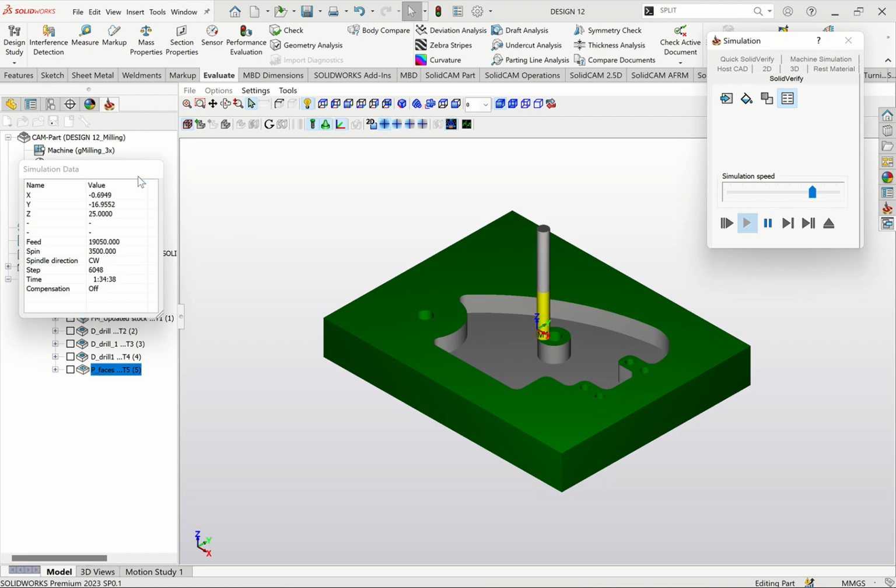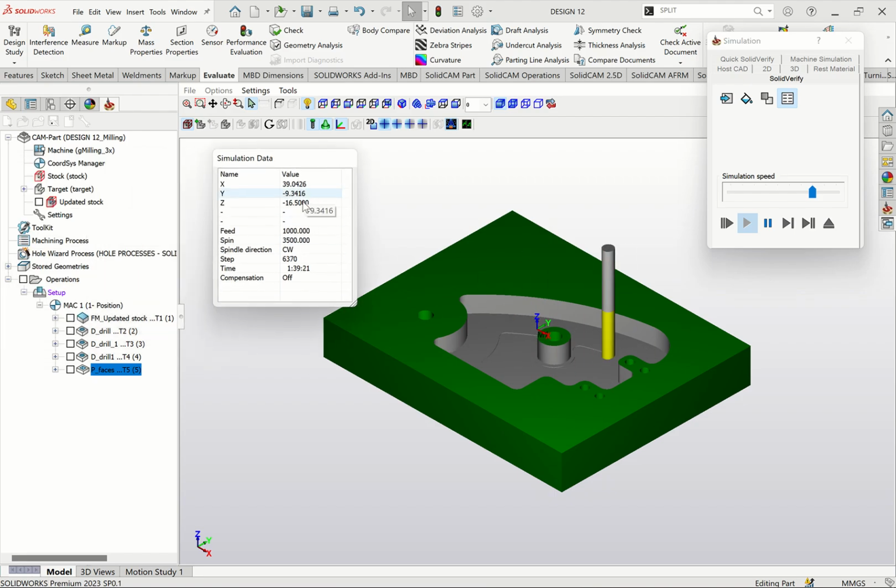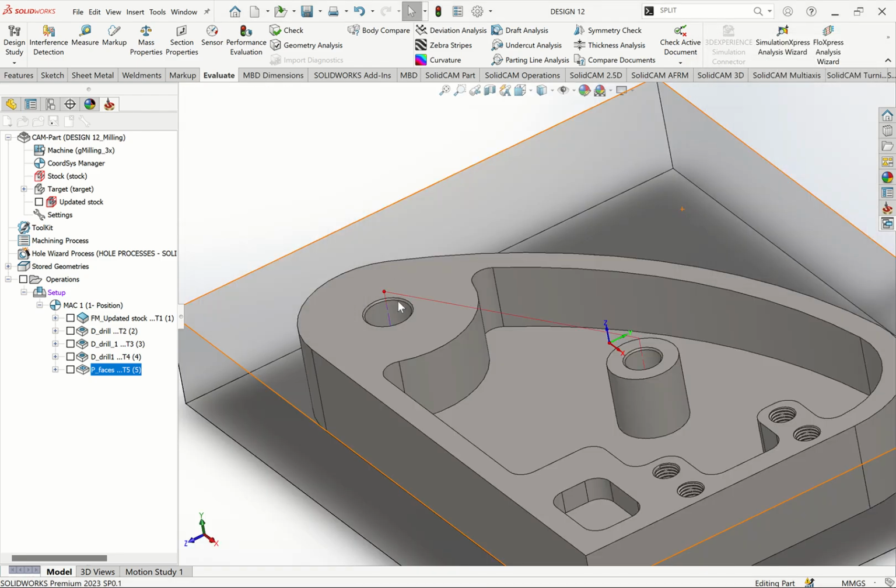Also here, it is showing the data, how it's cutting and the depth. So up here, Z is the depth. So you should go up to 24. That was 20. It was 20. So it should go up to 20, then it stops. And I'm using 12.5. Now see, it is on 20. Now it's finishing. Yes, it has finished. Then it goes up to 25 at the safety.